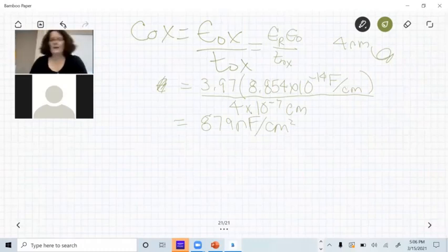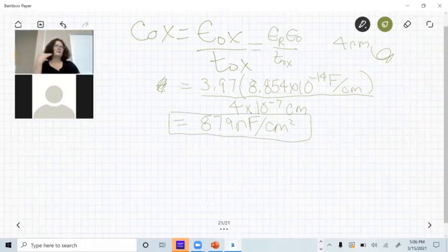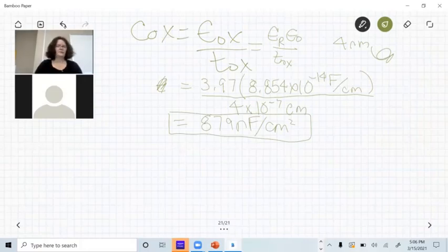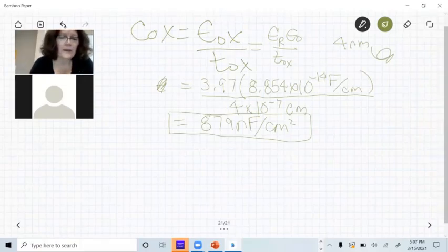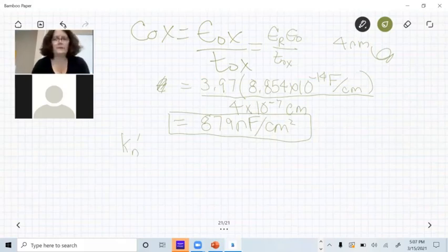The next number that we had to calculate, we'll talk about this transconductance parameter later. It's related to the gain of the transistor. We have 2 types of this. There is Kn. I just want to talk about units. Kn prime, which applies to every single transistor that I get out of the process on that day. It's called the process transconductance parameter.